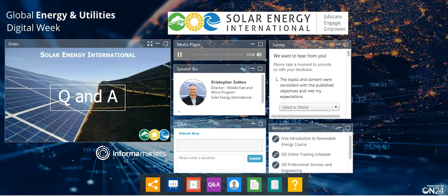Okay, so when we go to the size of an inverter, first thing we've got to do is understand what our application is, just as I said at the beginning. We size inverters differently based on whether they're battery-based or utility-connected. If we put those into 2 categories for starters: if it's battery-based, it means we have to use the inverter to run the load. So anytime we have a battery-based system, whether it's an off-grid standalone system or a backup power type of system, we're going to size the inverter based on two things really.